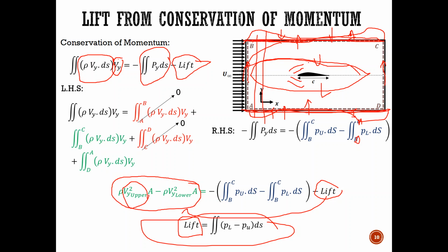In other words, it introduces what is called blockage, B-L-O-C-K-A-G-E, okay? And because of this blockage, the lift data that you get from the force sensor will not be accurate, okay? That's why people usually rely on the static pressure measurements, this PL and PU static pressure, on the surface area so that they can determine the actual lift that the airfoil creates, okay?